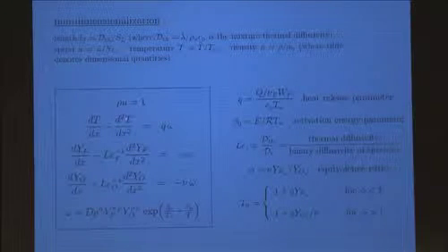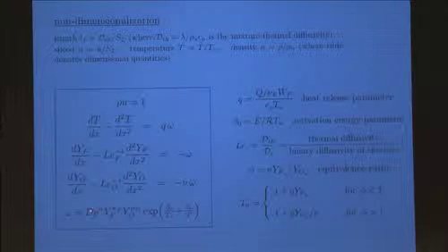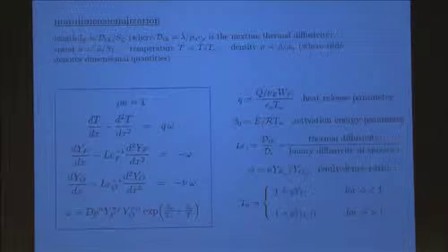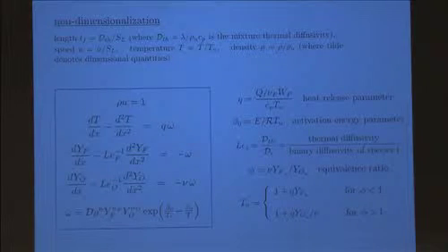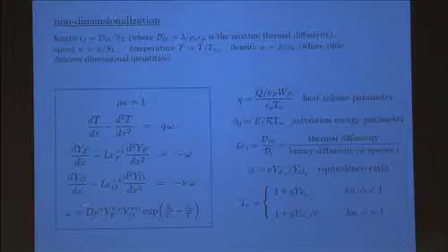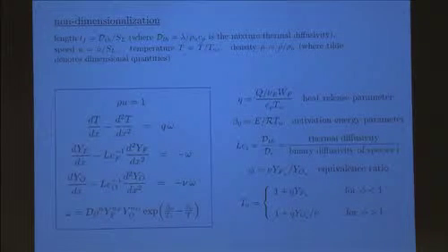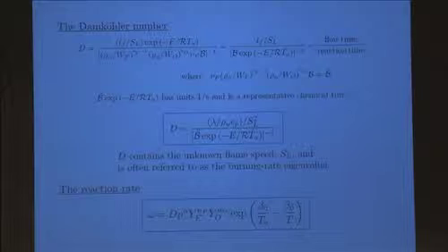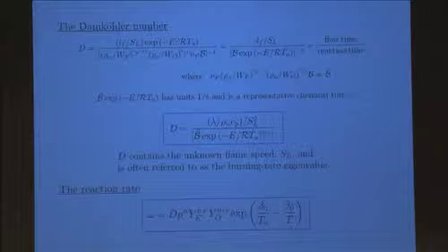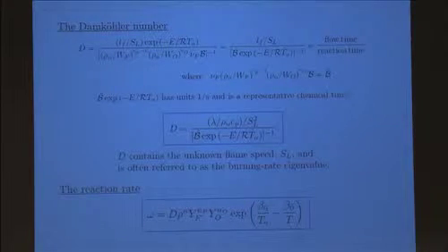In other words, solving for the temperature, the mass fraction, as well as this unknown D, which is known as the burning rate eigenvalue. It's an eigenvalue problem. In other words, part of the unknown is to determine this D. And just to remind you, the D contains the laminar flame speed, so that once we know D, we can write an expression for the flame speed, and that's the objective of this discussion, this analysis.